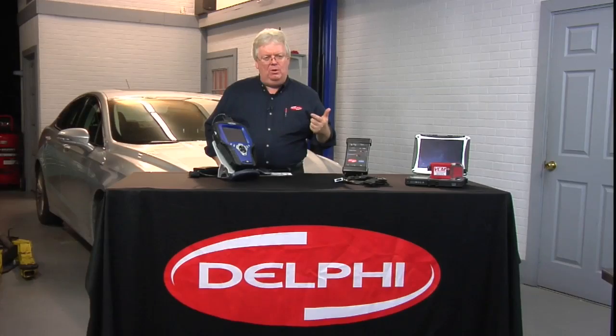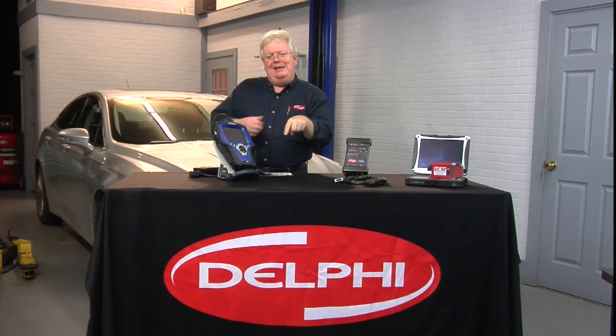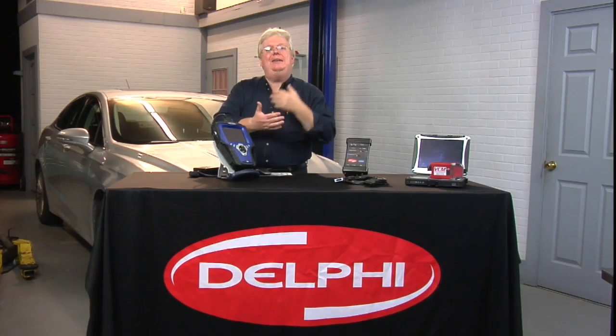I got a question here. It says, how long does it take to run monitors? Well, it's going to depend on the type of monitor we're looking at. Depending on driving styles and habits of the customer, it can take days, even weeks. I've even driven across the state of Texas in several different OEMs with either the gas cap off, or on the capless cars, a little Allen wrench shoved down to open up not just the first little flapper, but the second seal that really seals it, and never set a light.